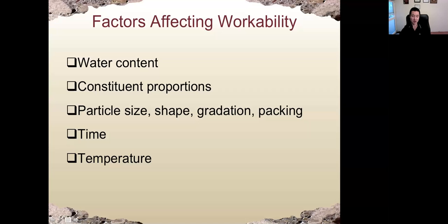Time, so how long after we mix the concrete we check the slump, is obviously also important because the hydration is time dependent. Temperature: at higher temperature, we have a faster hydration speed. So the workability at a certain time will be lower if the temperature is higher.